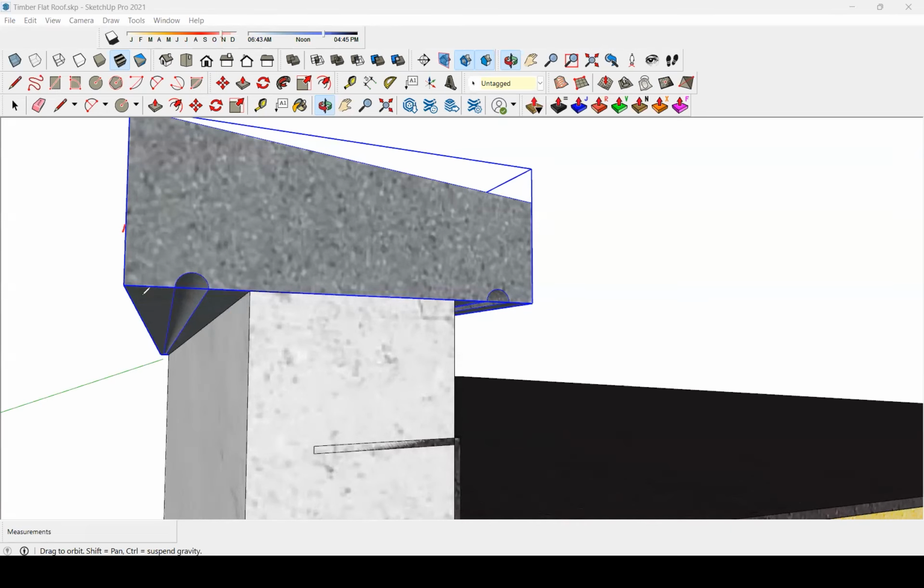So the water drip channels the water in this direction. It goes through the drip, and when it gets to the high point in the drip, it just drops due to gravity. That means the water drops without staining the wall. It drops in space freely. So that is the purpose of the water drip detail.